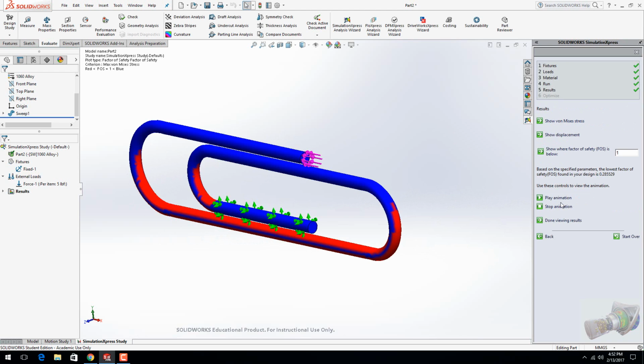Yes. Okay, the first thing is you have the show factor of safety. Factor of safety is a calculation based on safety, essentially. For example, aircraft or aerospace equipment might be tested at 1.5. That's because they have to be lightweight and have the characteristics so they could fly or things like that. Versus automotive industry might use 3.0 for their factor of safety. So in this case, we'll go with 3.